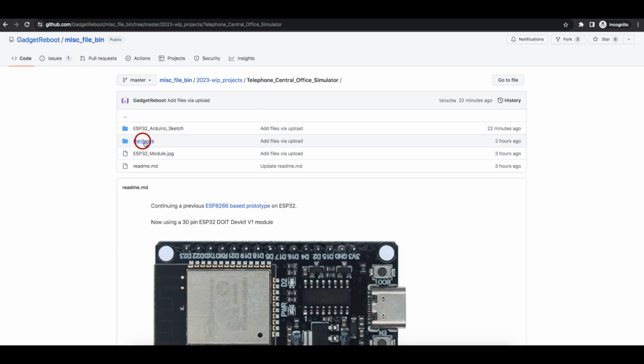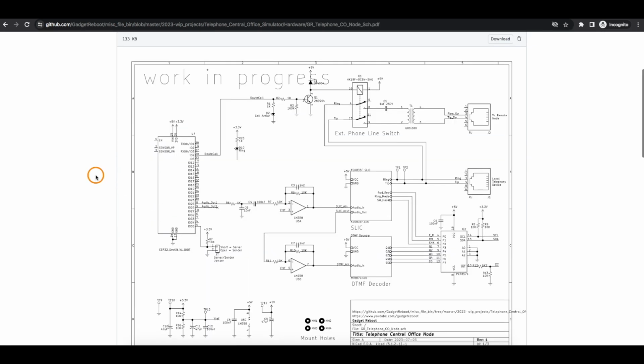So in the hardware folder on this temporary GitHub location I set up for the work in progress, all I've really done is delete the ESP-8266 module and put the ESP32 in. So I have the audio output pin for Mozzie sound generation. And I've also got this configuration jumper now. This is new. We'll look at that. And the rest of this is really not yet changed.